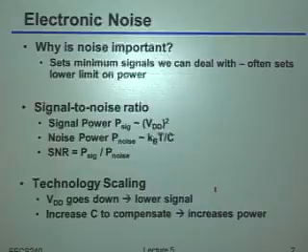It turns out that, especially in the analog circuits we're going to be talking about, or rather, if you're even going to be dealing with analog circuits in the first place, in many domains the fundamental noise you have in electronics sets the minimum power consumption that you have to dissipate to get your circuit to work. In other words, you have to understand noise very, very well to be able to do low power circuit design, and again, that's many of the contexts we're going to be interested in.